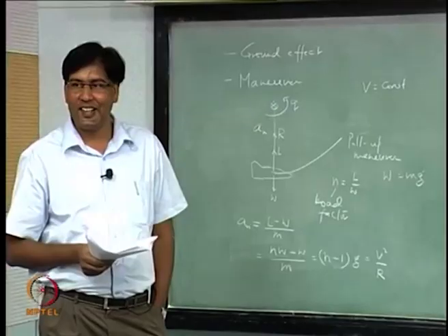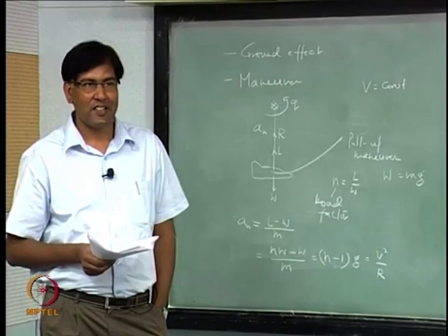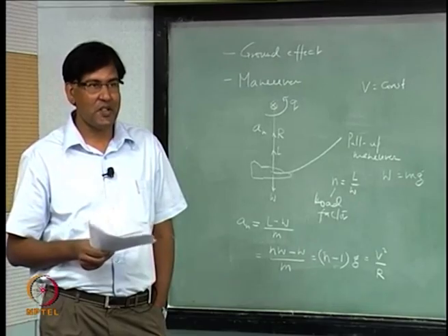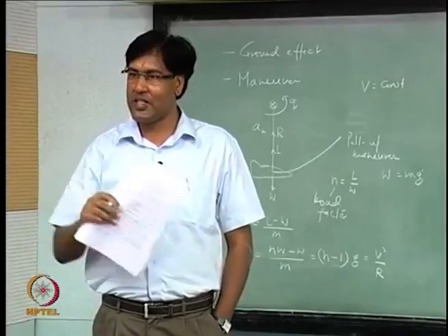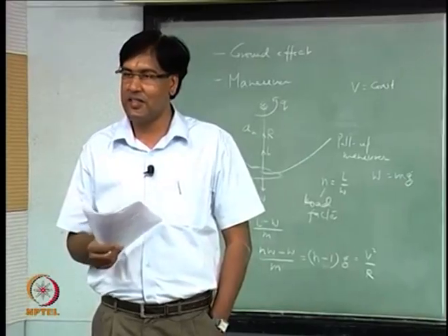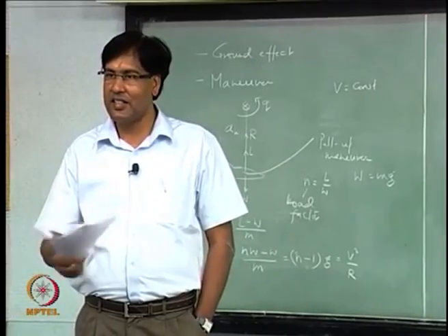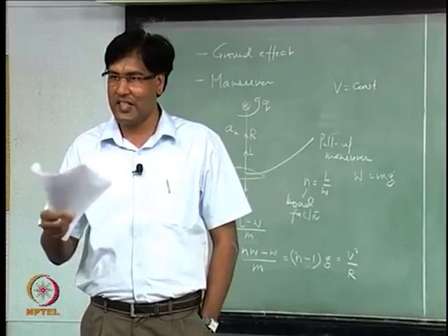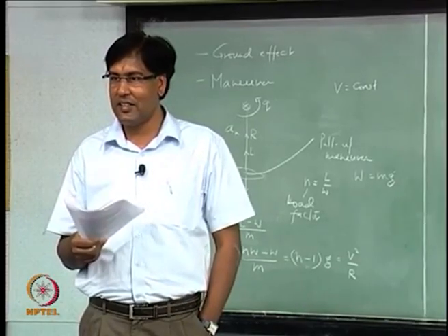The angle of attack? Where? At this time only the elevator will change. Don't change anywhere else. Angle of attack is going to change. Where? Let's say I'm giving a delta E which is causing a pitch rate, right? Because of that, what is changing? Angle of attack is the right answer. Where is it changing? In what ways?